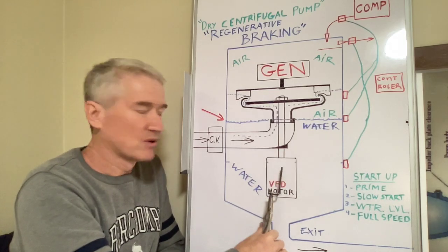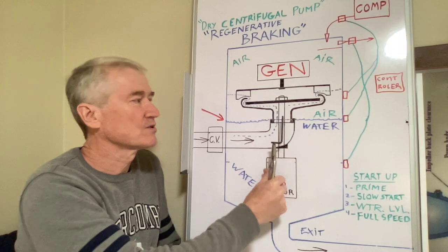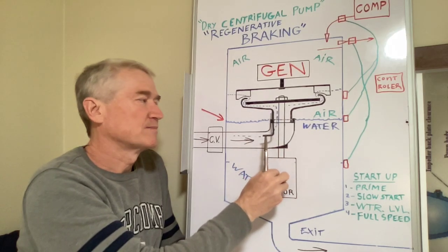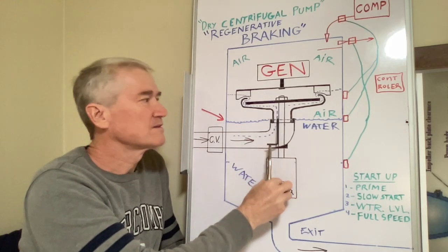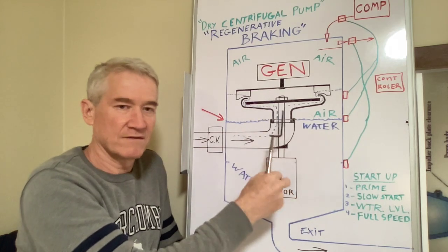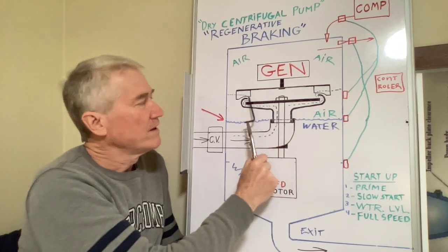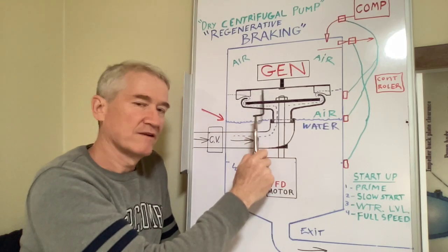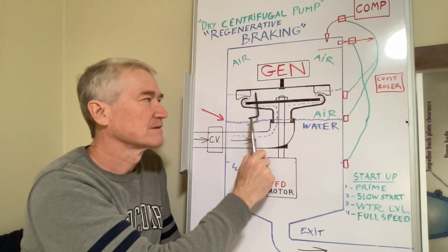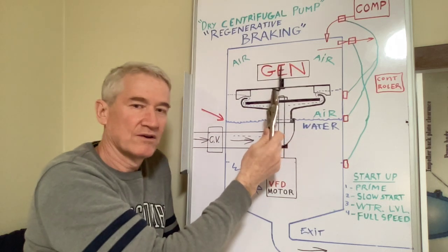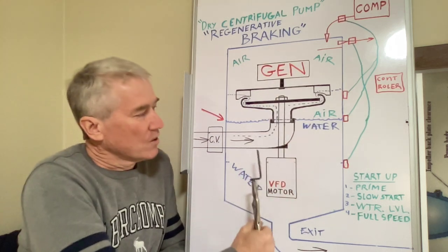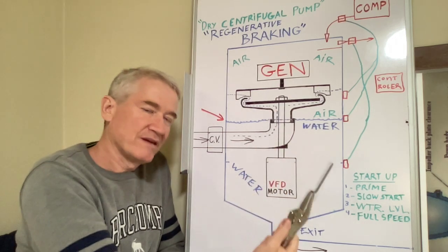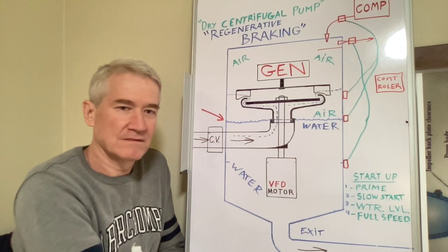There's inefficiencies in the motor itself, inefficiencies in the seals, the bearings, then the closed and trapped impeller has inefficiencies and friction inside, viscous drag, turbulence. Then when the water comes out, it goes through the air to the turbine, which has inefficiencies in that, and then there's inefficiencies in the generator itself. So what I'm looking for is, outside of these losses, can anyone think of more losses that I haven't calculated in?